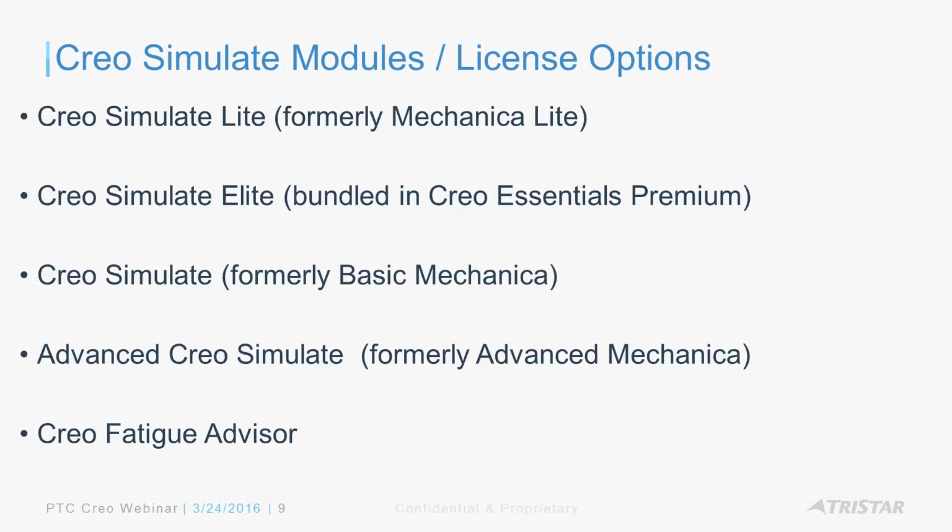From a licensing standpoint, I just wanted to quickly touch on the different license options available for Creo Simulate. Anyone that has Creo Parametric is able to run a basic analysis, like a static analysis, on any part or assembly that has less than 200 surfaces without any add-on license. That's the Creo Simulate Lite. As soon as you launch Creo, open up your model, and take it to Simulate, you can turn on the Simulate Lite, which allows you to just run the analysis using a guided interface.